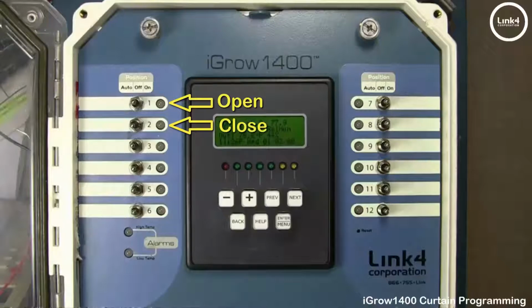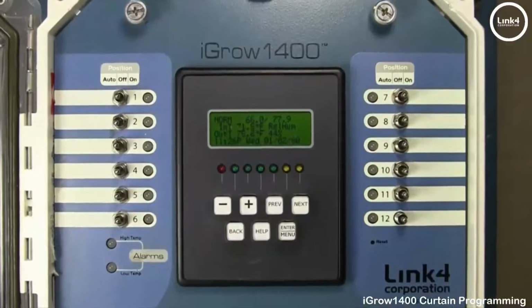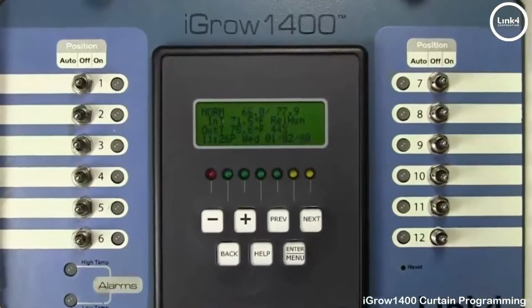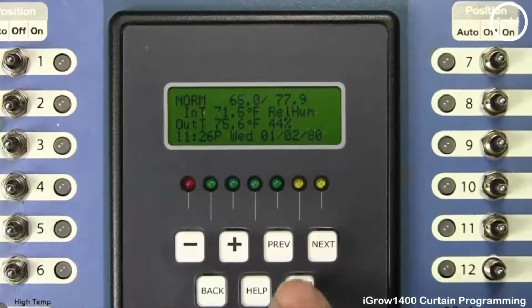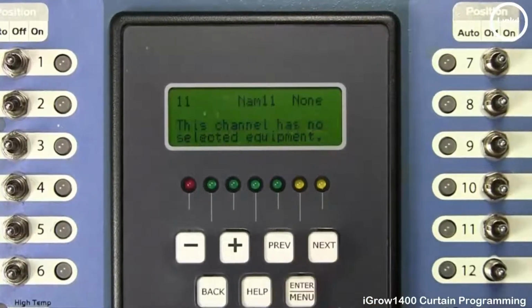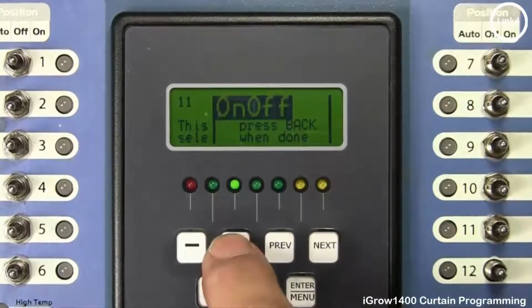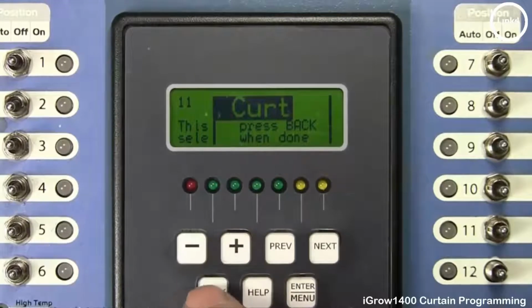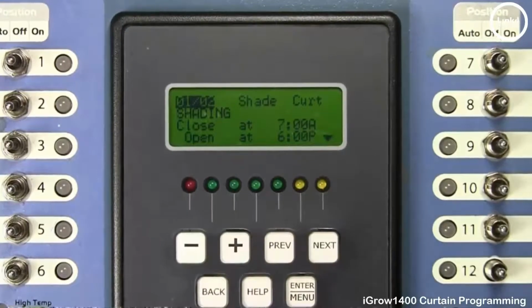Now with curtain programming, you have shade control and you have energy control. But first thing we're going to do is go ahead and program an output to be shade. Now from the home screen, we'll simply hit Enter Menu, go to Program Equipment, and as you can see, output 11, we're going to hit Enter Menu, hit Next a couple of times, expand the none, and make this output a curtain output. Now what we've done, we have already made output 1 and 2 a shade curtain output.